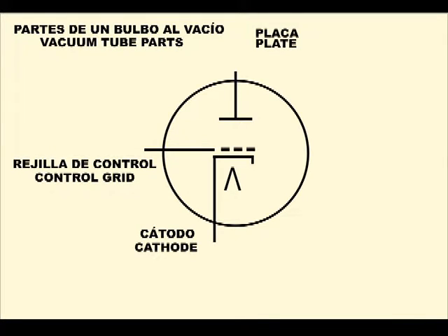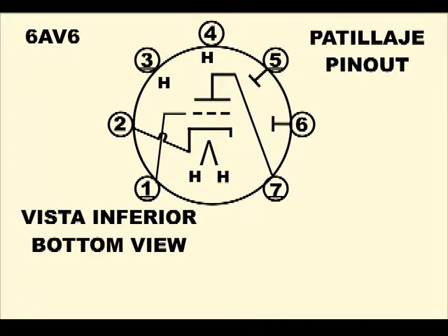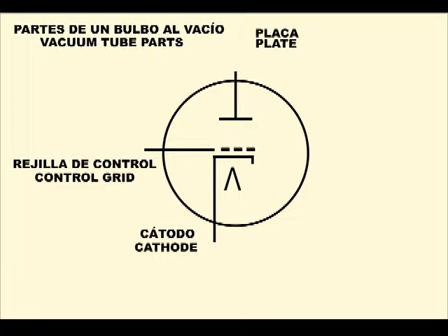The triode is the first amplifier tube that was invented. It consists of a glass bulb with 3 elements or electrodes inside. The triode we will use is identified as a 6AV6, which in the 1950s was widely used as an audio amplifier in radio receivers. In this diagram, electrodes are identified by their most common names: cathode, grid, and plate.